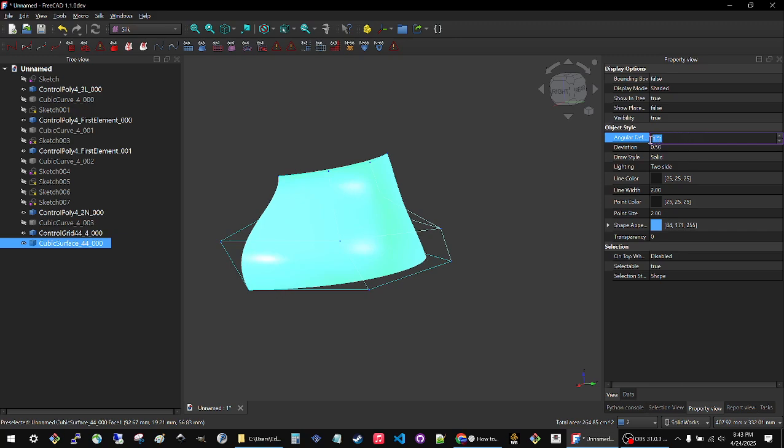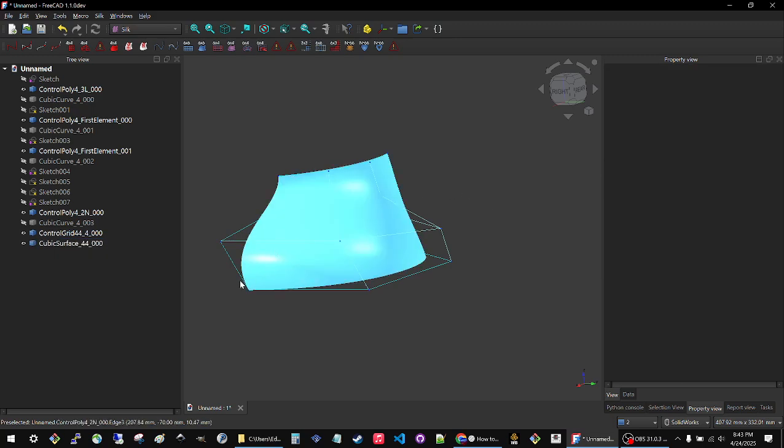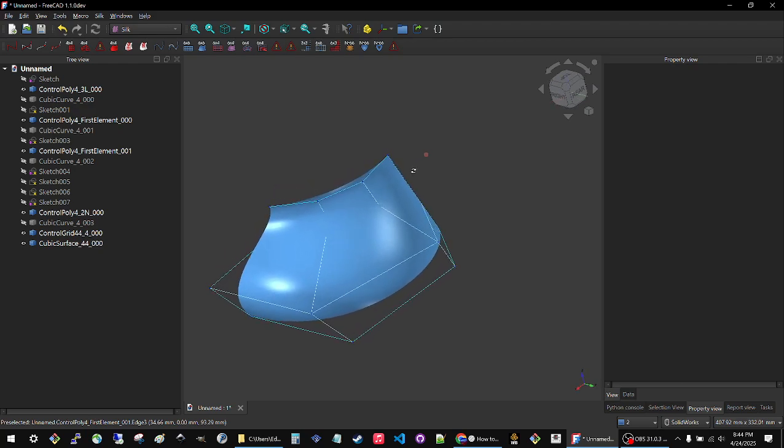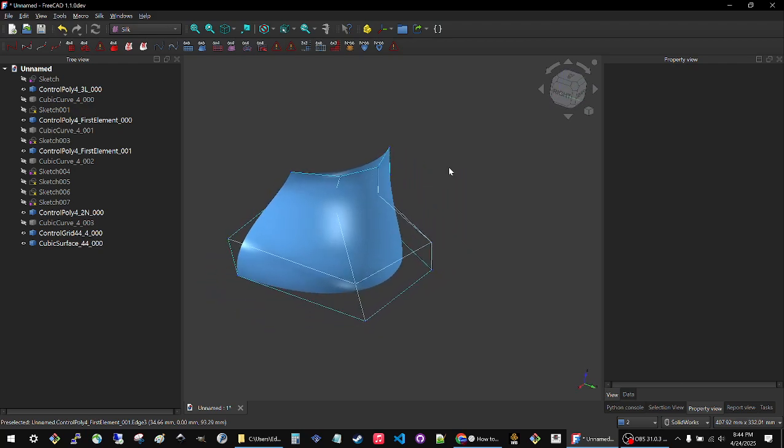Oh, FreeCAD was hanging on me. I don't know why it took so long. Let's do 1 degree, hit enter, and then here, this 0.5, I'm going to make that 0.05. And see how long it's taking to react? Ugh. And now, look at that. That is much prettier. You see how everything got way smoother right here? Everything got way smoother. And now the real fun begins.